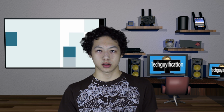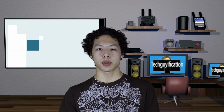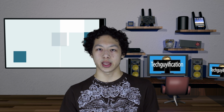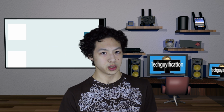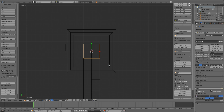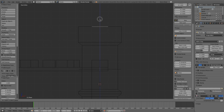Now select the tower with right click, and then press Shift S, and then snap the 3D cursor to selection. So this is going to put the 3D cursor at the origin of the object which we centered earlier. Now press Shift A and add another plane object. Go into front view by pressing numpad 1 on the number pad, and then use the blue arrow to move the plane we just created slightly above the tower as shown. Now press the S key and scale up the object to approximately the same size as the tower.